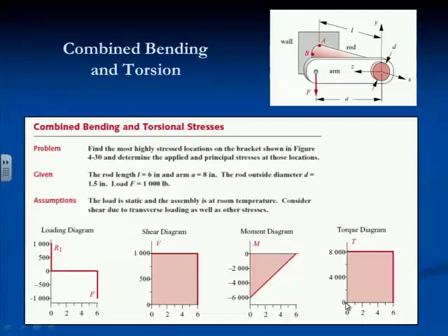That's good. So what about B? Yes? You will have the same magnitude of stress as at A, but in a 90 degree direction. Yep. What else? He's saying that we have torsional stress at B, the same magnitude as at A, but 90 degrees from the way it was at A, because it's around the corner. Yep. If B is at the center, the neutral axis, yeah, the normal stress would be zero. Normal stress is 0, that's correct.